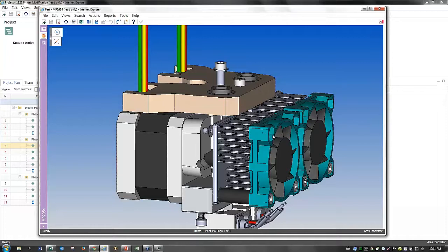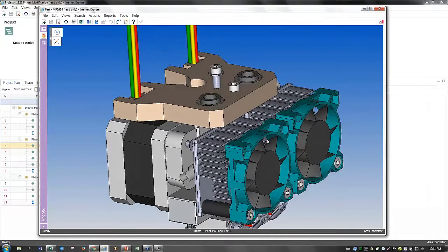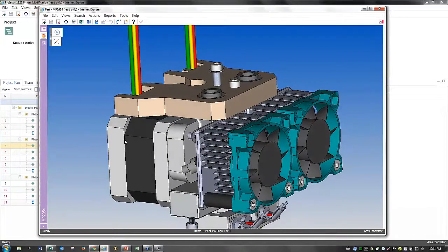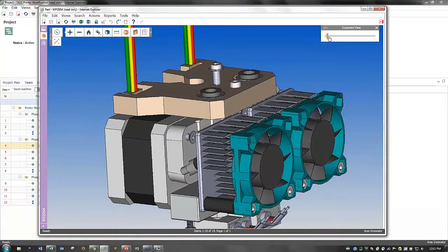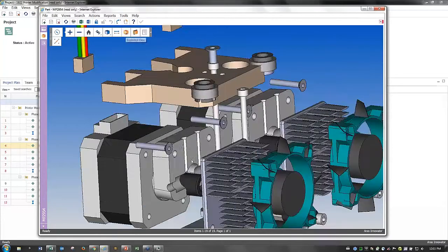This kind of happens behind the scenes, where there's a conversion server that's converting this 3D into this viewable format. But what I can do now is that not only can I mark it up like I did the document itself, but I can go in and explode this view, these parts out. I can also take a look at a specific plane or a cross-section, and I can zoom in through the X, Y, Z. I can also take off the exploded view and come back to my exploded view.